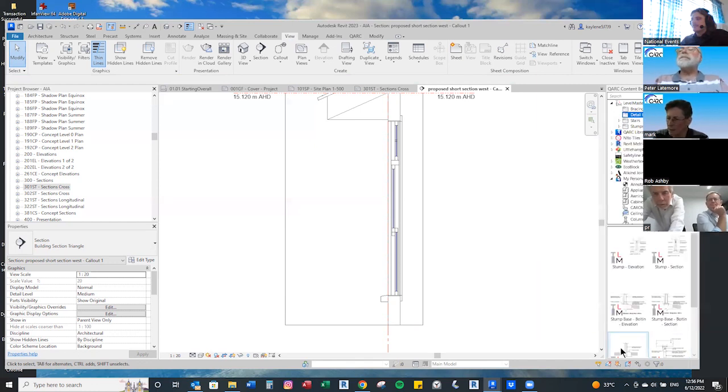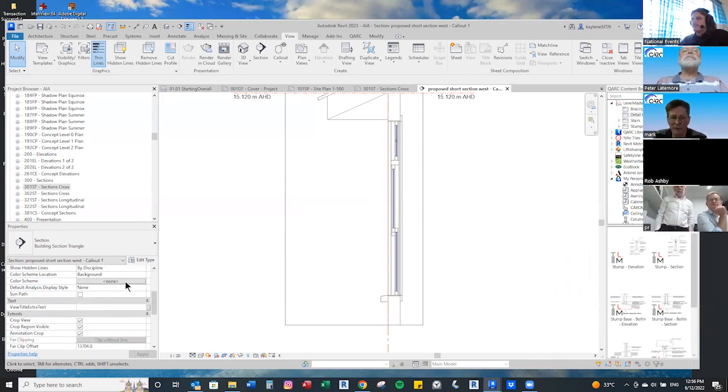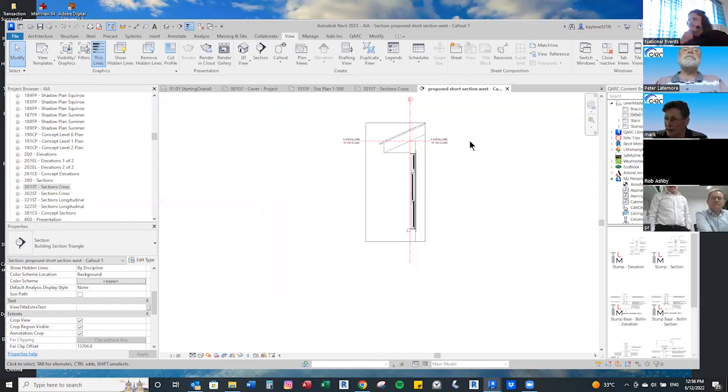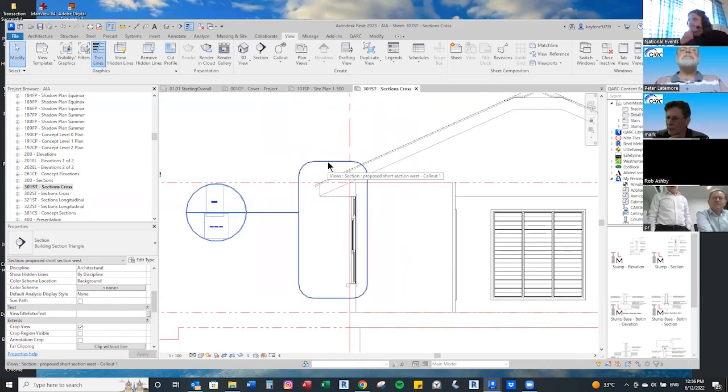They're so easy. In my documents, if I cut a section through, I click on all that stuff and override it so it's virtually transparent and disappears. And I draw the 2D in paper space, if you want to use an AutoCAD term, over the top. That way I actually know the detail works. Too often architects do lovely little details that actually aren't to scale. So when I'm doing a brick veneer or something like that, I'm literally doing it to scale. The problem is when you update the model, it potentially doesn't align with that. But if you look through my set, I've got about 50 sheets where I literally do that. If you change something, you have to update it. But it always needs to be 2D.